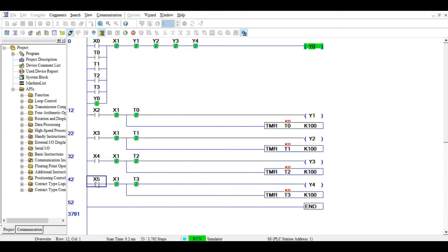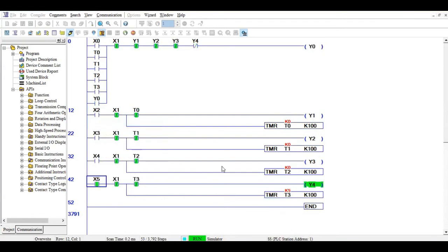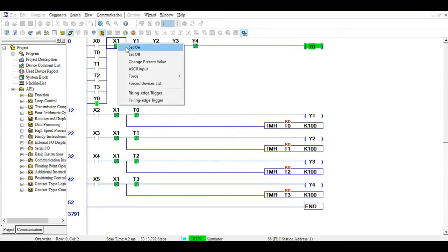After it goes through the water sprinkler, it will proceed to the dryer. X4 will be turned off, X5 will be turned on. Once the stage 4 sensor detects the car, the dryer will turn on, and it will be turned off after the timer reaches the time set. Here, once we click X1, the stop button, it will stop the running conveyor motor in our car washing system.